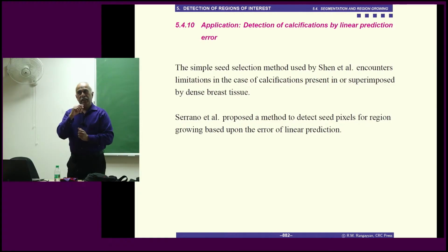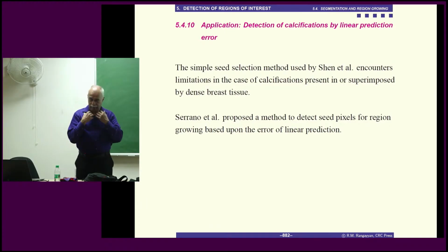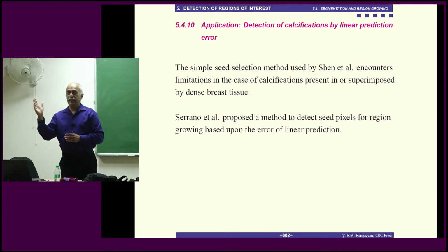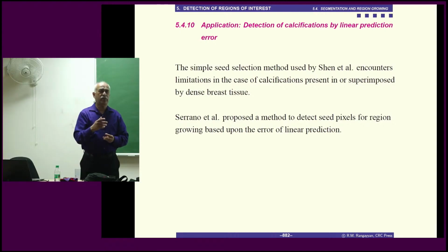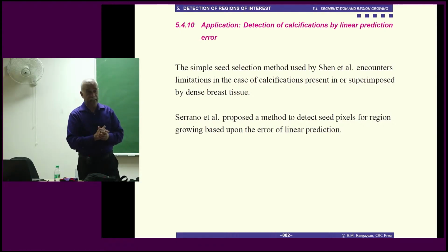So tracking the linear prediction error can help in identifying changes that are marking points of non-stationarity or a different process generating the signal. The same speech, but a vowel versus a fricative, voiced versus unvoiced or plosive signals. So you mark the boundaries and you segment the signal. That's commonly done in speech signal processing. You can do it with heart sounds also. And you have examples in my other book on biomedical signal analysis.